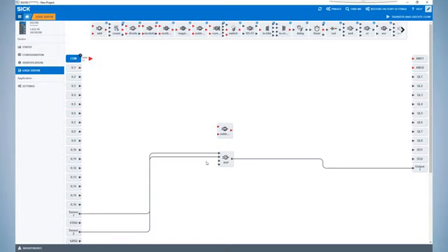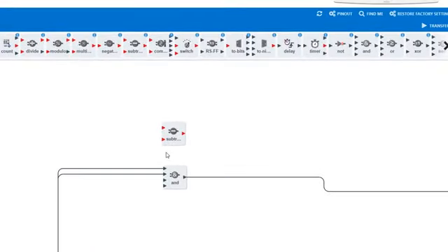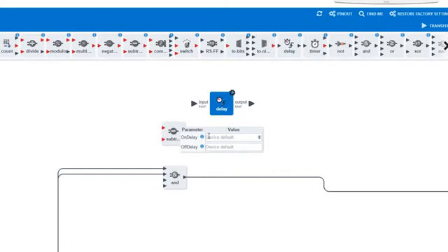Last, some outputs, inputs, and logic gates have a small configuration gear in the upper right corner of its block. This indicates that additional settings are possible. Clicking on the gear will open the Additional Settings dialog box where application-specific settings are possible. An information icon provides more detail on a given setting so the user can properly adjust for the application.